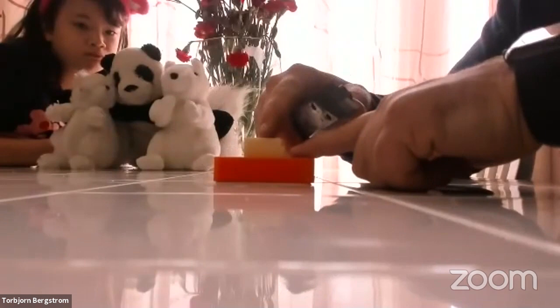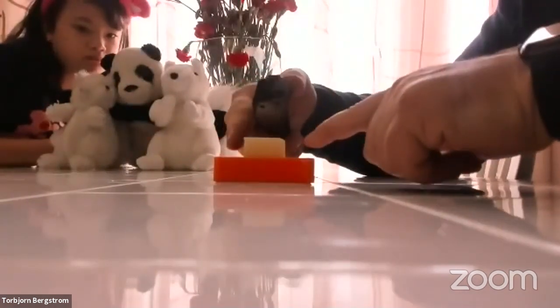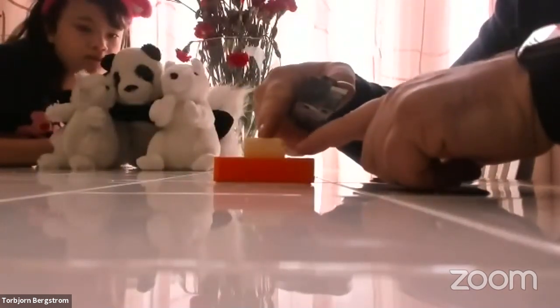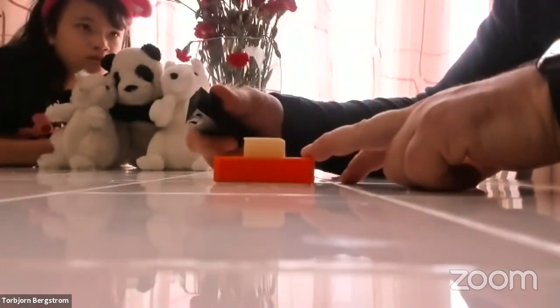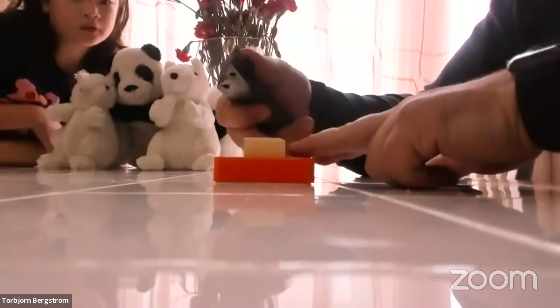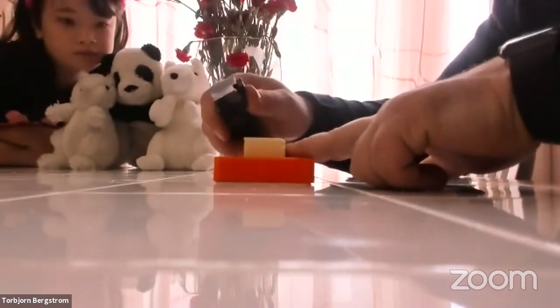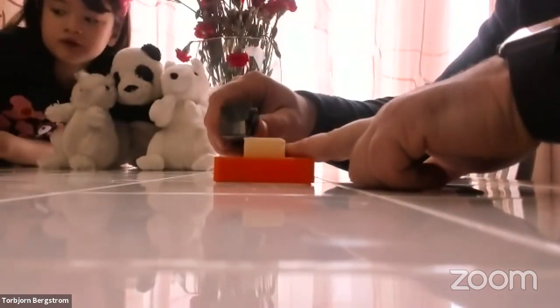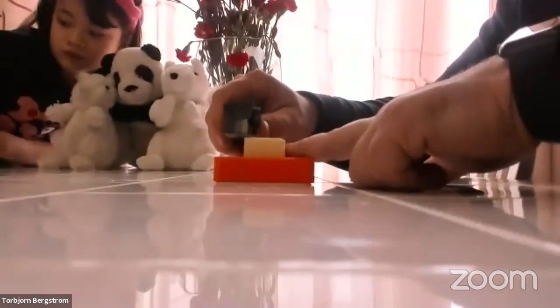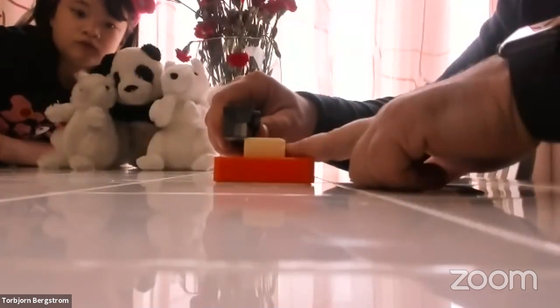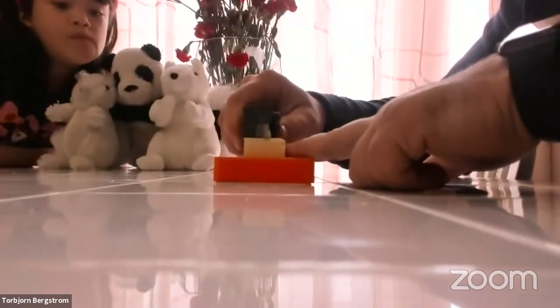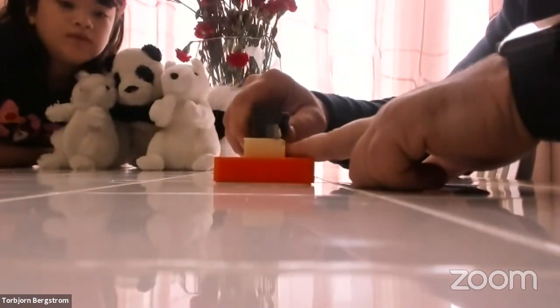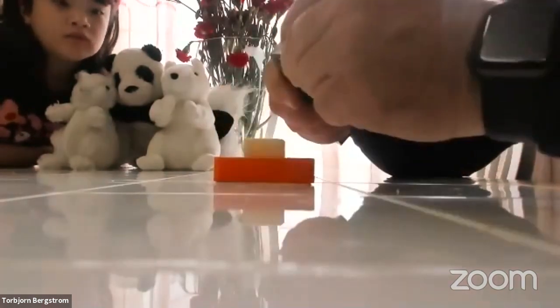All right, so we've got our workpiece, we've got our fixture. I know that this fixture may be not quite good enough to hold the workpiece, so I'm going to apply a little bit of extra fixturing force with my finger, and then we're going to slowly take a chip across the top of the workpiece here. And you can see the chip form on the edge of the workpiece and flow up the rake face. Emily, could you take care of that chip for me? Okay.